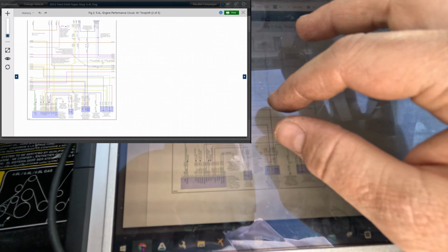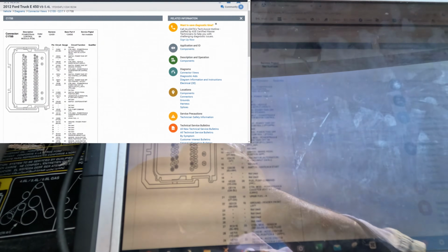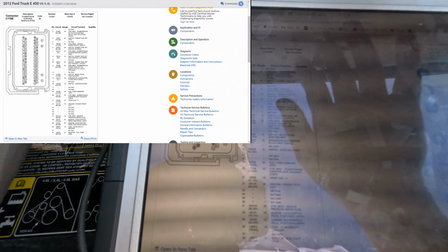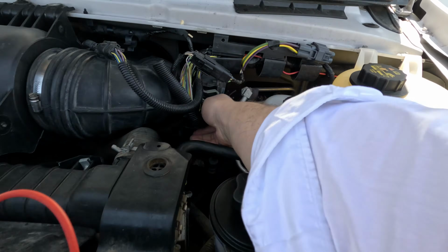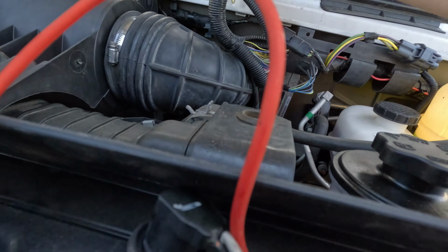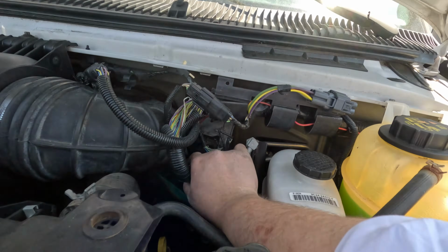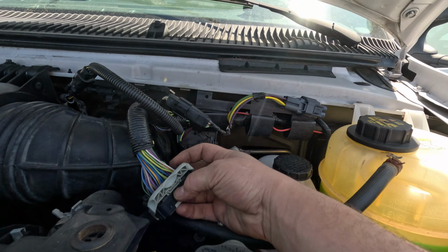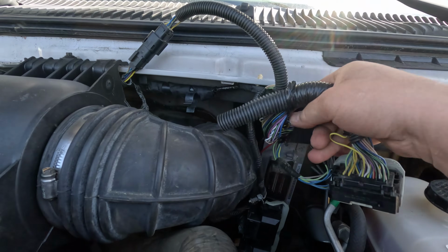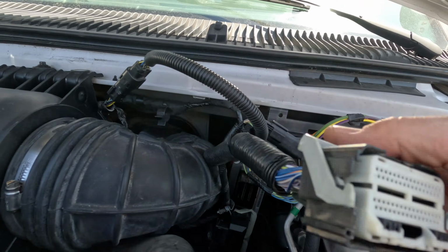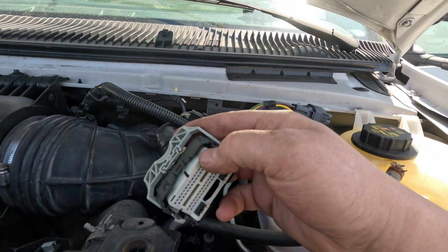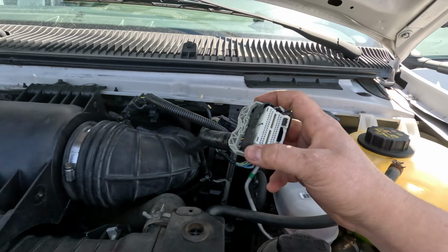So let's go back here. We'll start off with 22, so let me disconnect this connector. Let's make sure the pin's there. It is this wire over here, so it's on that side. None of the pins look bent. So this is pin 1 over here, right? We need pin 22.